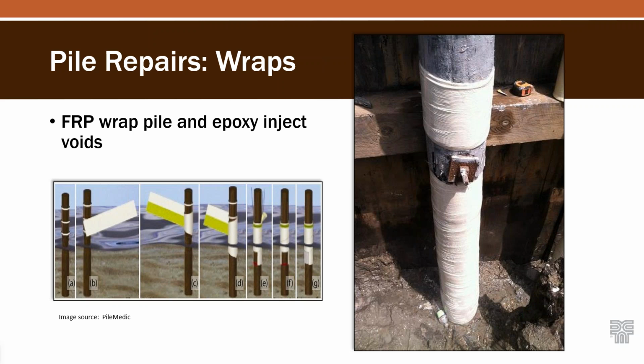Okay, so what do you do, right? We're going to run through a bunch of different repair options here. So pile repairs will be the first one. There's lots of different ways to repair piles. They're probably the most prevalent timber member across the country, right? Because a lot of times you have timber piles, but you have other things installed on top of them, like concrete, steel.